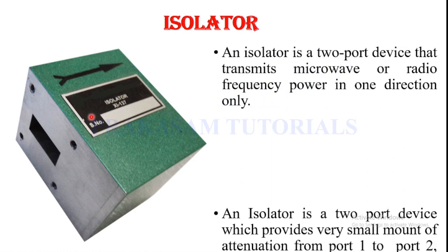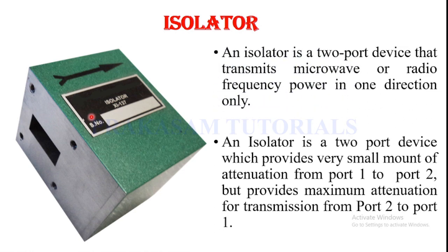An isolator is a non-reciprocal transmission device that is used to isolate one component from the reflections of other components in the transmission lines. An ideal isolator completely absorbs the power for propagation in one direction and provides lossless transmission in the opposite direction. These devices offer low insertion loss and high isolation over a 1 GHz bandwidth.